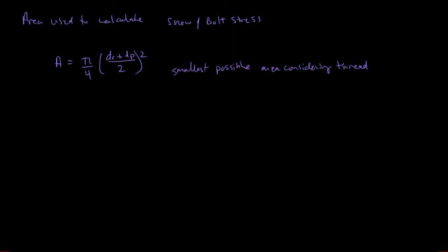One of the differences between UNC versus ISO is that the UNC for sizes less than a quarter inch, they use numbers, and the numbers are a number 0, number 1, number 2, and then it goes all the way up to a number 12 size.